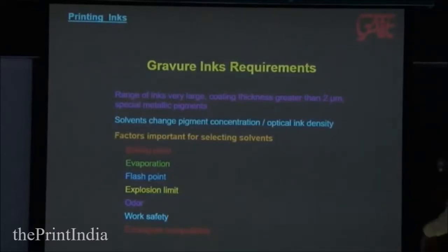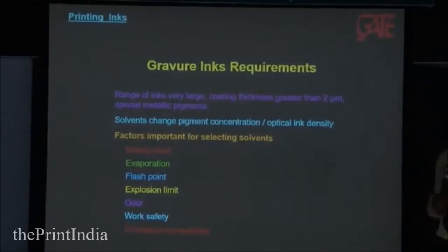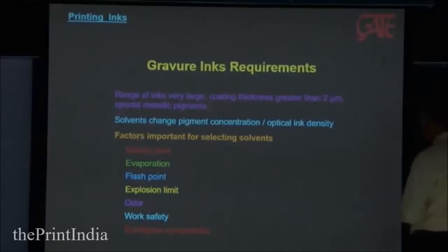Factors most important in selecting a solvent: What is the boiling point? What is the evaporation rate? What is the flash point? Explosion limit? Odor? It's very important when it comes to packaging. Work safety and ecological compatibility.